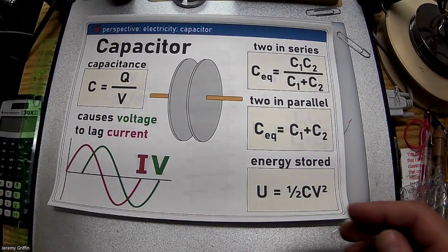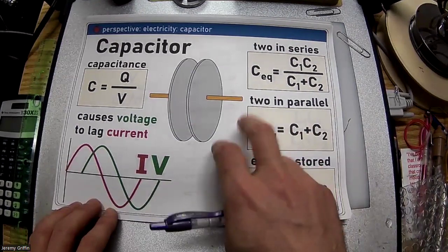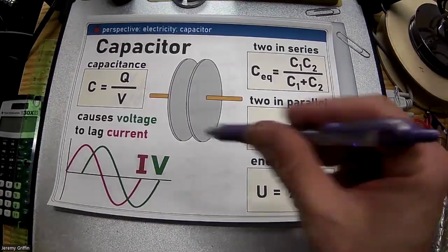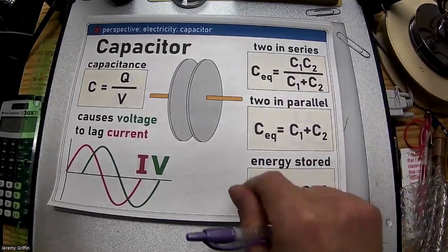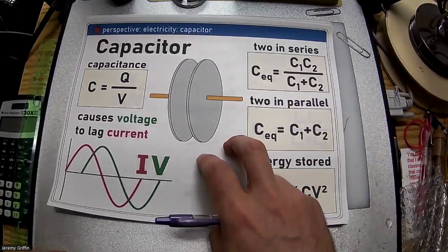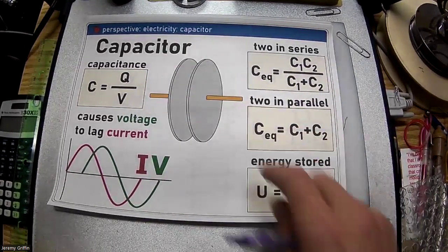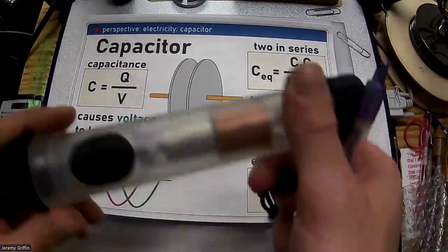Right? If you have an electric appliance with capacitors in it, say you have an old TV set, and you're like, hey, I'm curious, I want to see what's inside this TV set. You take a screwdriver and start unscrewing it and pulling it apart. That could actually be dangerous, even if the set is not plugged into the wall, because there could be significant energy stored in these capacitors. Okay? Kind of an example here.